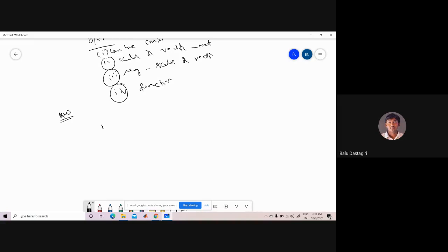First, module dataflow. For an AND gate, the inputs are A, B and the output is Y. Therefore I am declaring the output and inputs, Y comma A, B, and the inputs here are input A comma B.